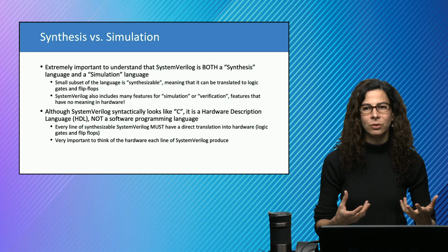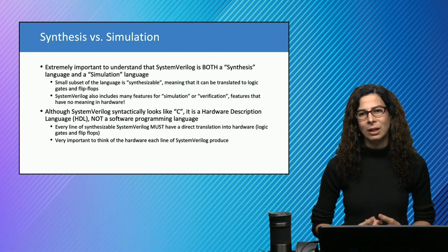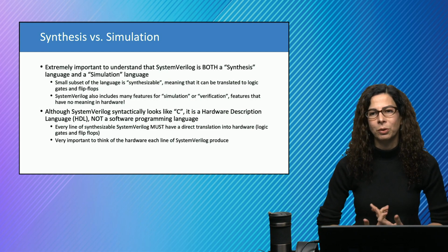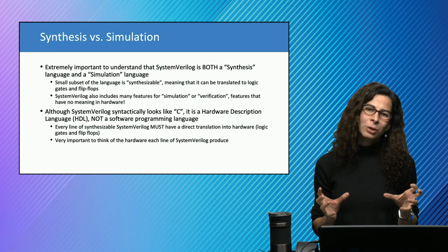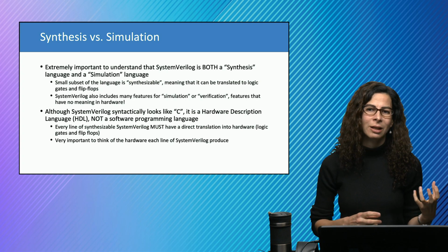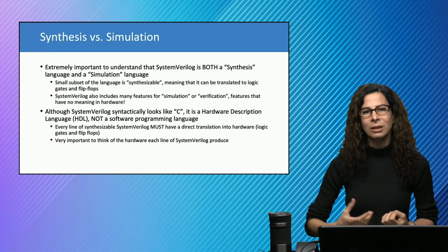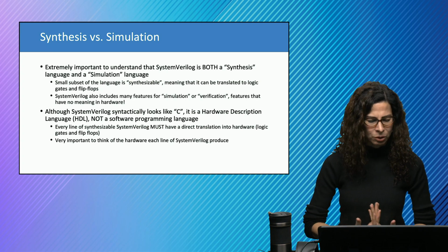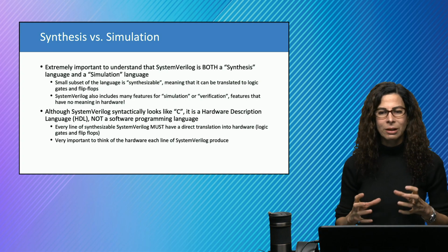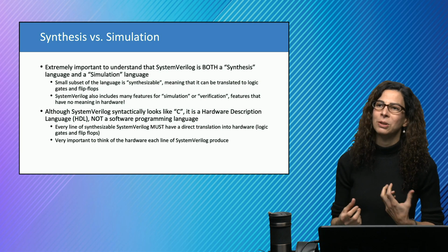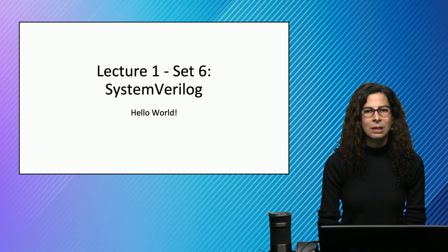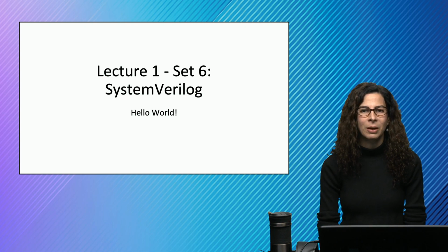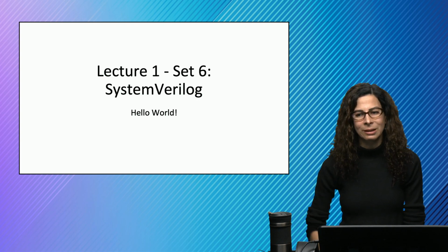You may want to load files into your simulation and write the output to a file. Some of these constructs are not useful for synthesis. So, in brief, there are many more language constructs used for simulation that have no actual physical value during synthesis. Synthesis is really about making hardware. So every time you write a piece of code, you're generating a piece of hardware. With that, we will be talking about the next set, the very basic SystemVerilog code equivalent to a hello world in the C programming language.